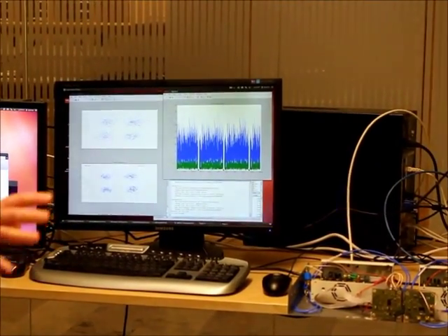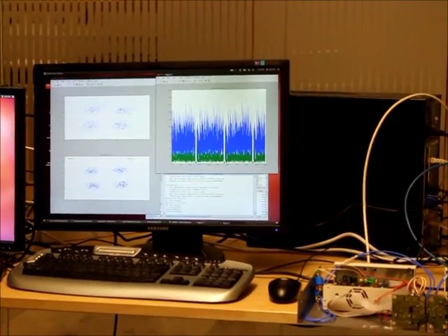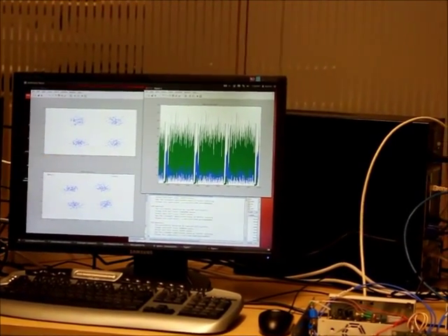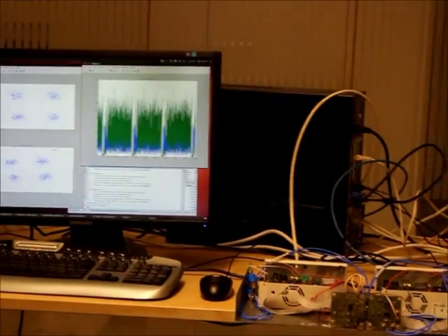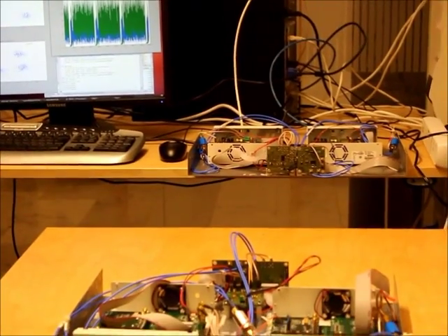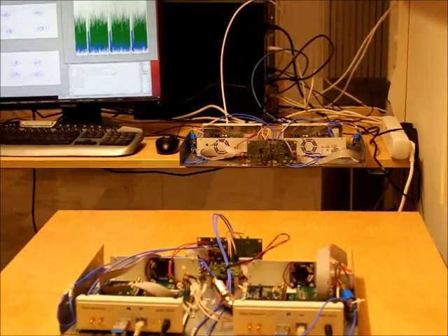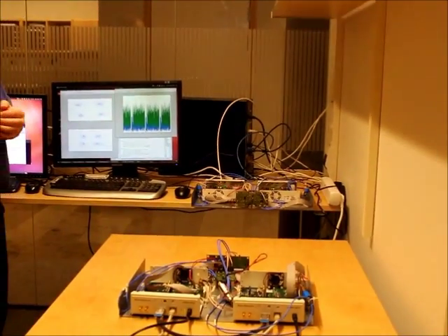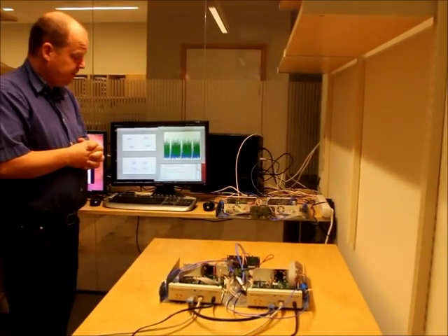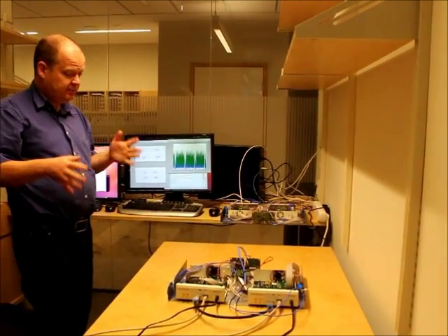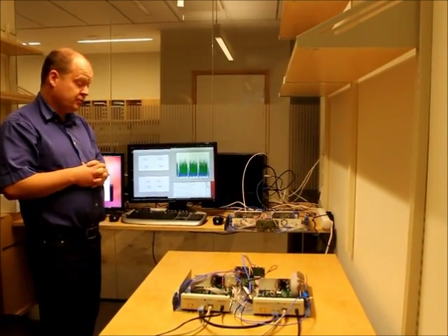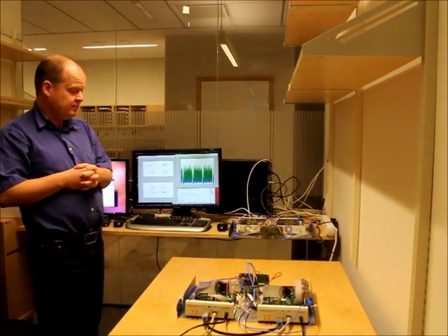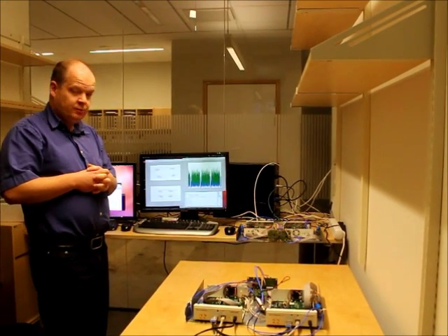We will make the design and software and hardware available openly, and we are also going to publish some measurements from this that can be used to test phase noise compensation schemes and other dirty RF aspects. For instance, this MIMO setup was done without any pre-coding at the transmitter, so just transmitting two streams on the two antennas, and probably this can be improved maybe with power control and other phase adjustments between the two transmitters. So thank you for your attention.